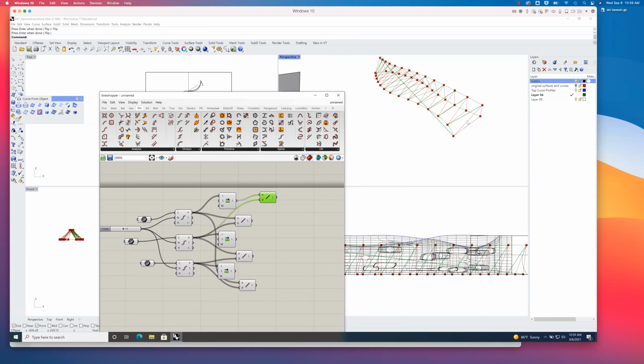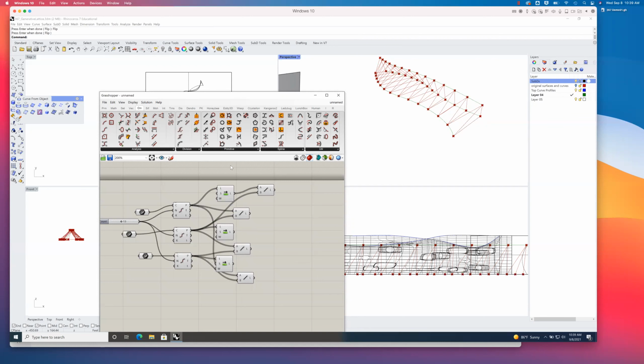What happens is when I shift the list over, it takes that first item and shifts it to the back and keeps it. So again, the first item and the last item are being connected here. So I'm going to go to these shift widgets, go to the wrap option, right click, set Boolean, and toggle it from true to false to turn the wrap off. Get rid of those. I saw that in a couple places. Not a big deal. I didn't take anything off. It's more of a learning experience at this point.